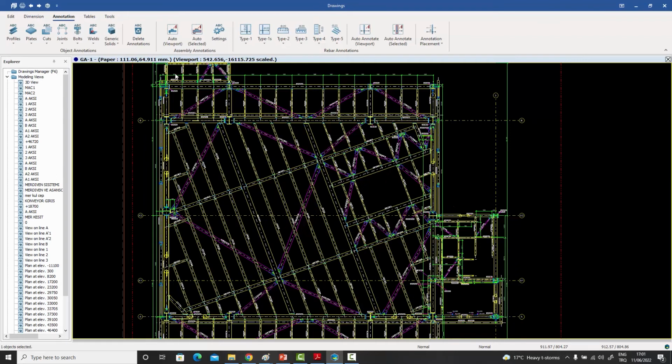Instead of that, what you can do is create these A0 drawings, for example, in which you have lots of viewports for all the plans and the sections, and all your joints are labeled there. And directly there, you can put in your maximum and minimum deflections and the load combinations which are creating those, or the profiles are also shown, and you can show how they're being stressed and which combos are stressing them the most.